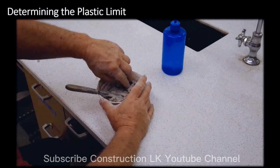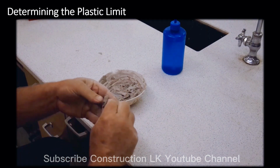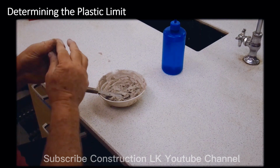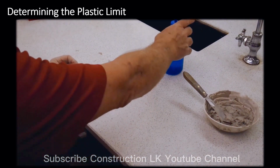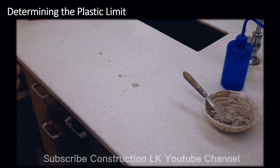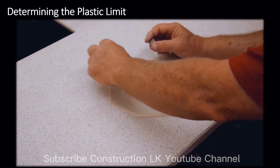Now let's move on to the determination of plastic limit of soil. The soil sample prepared for the liquid limit test can be used for this test. Here the moisture content of the soil should be reduced to a consistency at which it can be rolled without sticking. From this sample, about 2 grams should be taken and formed into an ellipsoidal mass.